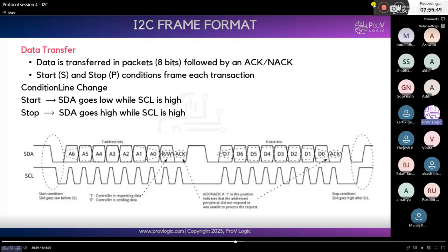That is what start and stop condition mean in UART protocol. Directly we keep 0 and 1 in UART, because we don't have the clock signal, we just have the baud rate. But in I2C protocol, we have SDA and SCL. That's why for these two, we write a common logic. Whenever SDA goes high to low while SCL is constantly high, it is start condition.